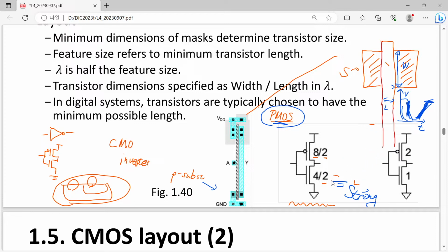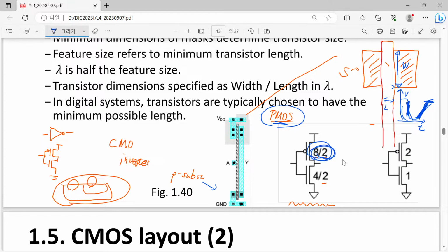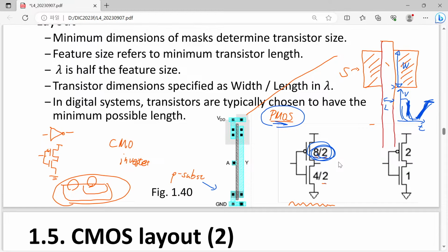Are you with me? And it really depends on the technology. Previously, the silicon's electron mobility and hole mobility showed somewhat of a difference, so even twice or even 3 times difference were observed. However, as technology evolves, we have invented a way to boost up the hole mobility in the PMOSFET, so the difference gap is not as high as before, but still we have differences. Okay.